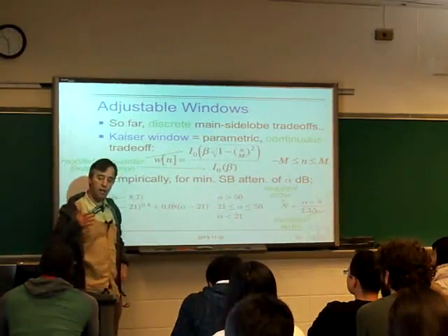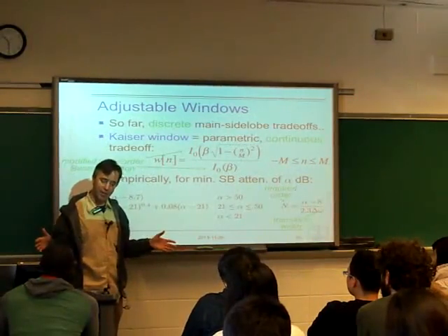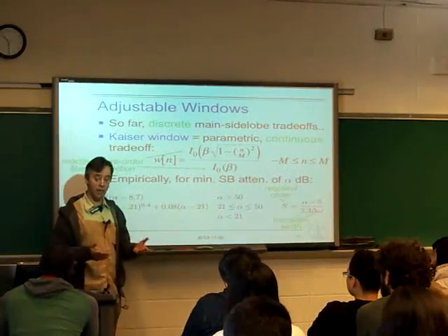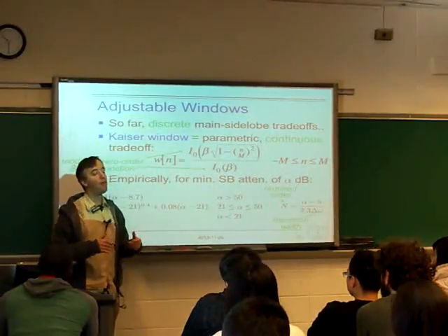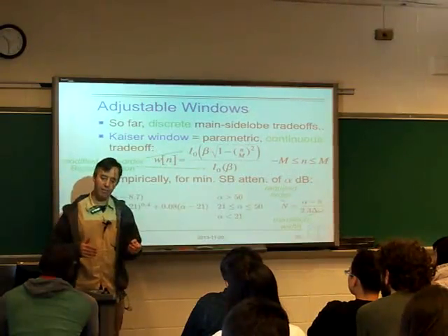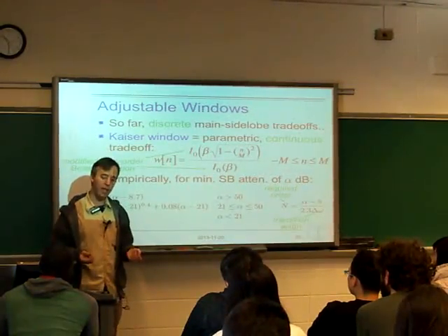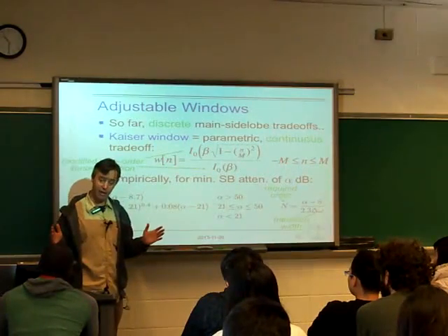So we could use a low-pass filter on top of the window function to get rid of the high-frequency terms in the window function, and then we'd have a new window function which would have less high frequency. But to apply that low-pass filter to the window function would mean convolving it in the time domain. And so we'd end up with a longer window function, right?